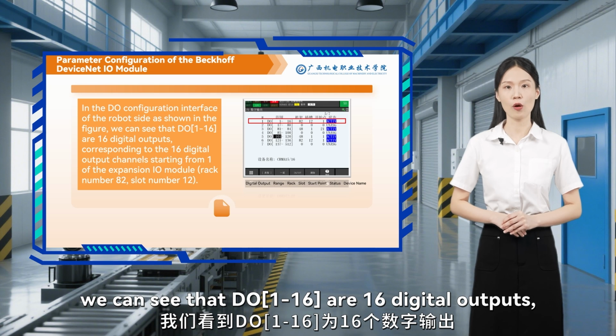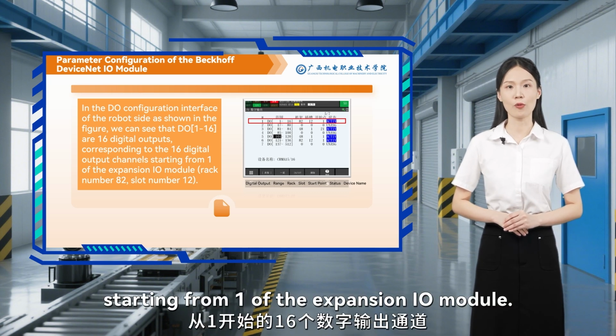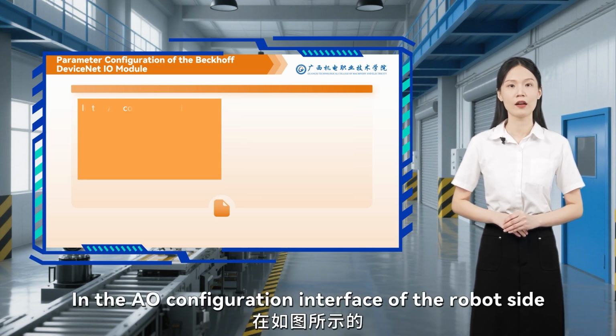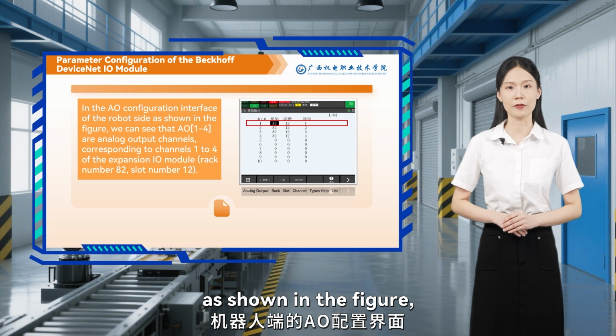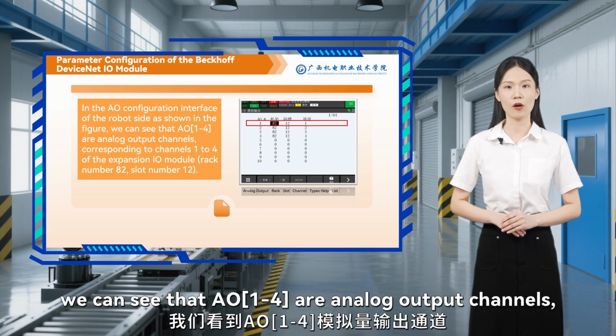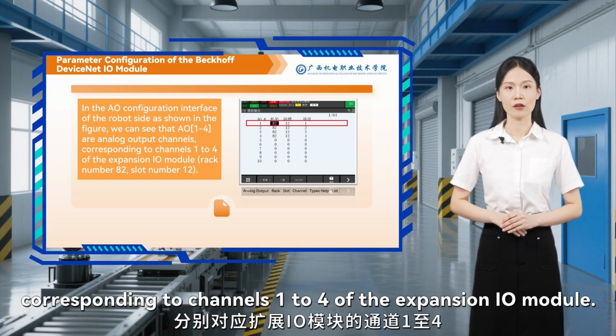In the DO configuration interface of the robot side, as shown in the figure, we can see that DO 1 to 16 are 16 digital outputs corresponding to the 16 digital output channels starting from 1 of the expansion I/O model. In the AO configuration interface of the robot side, as shown in the figure, we can see that AO 1 to 4 are analog output channels corresponding to the channels 1 to 4 of the expansion I/O model.